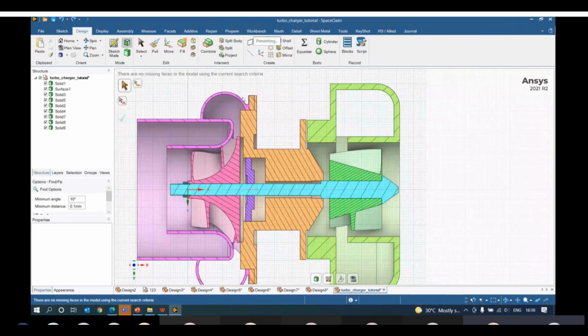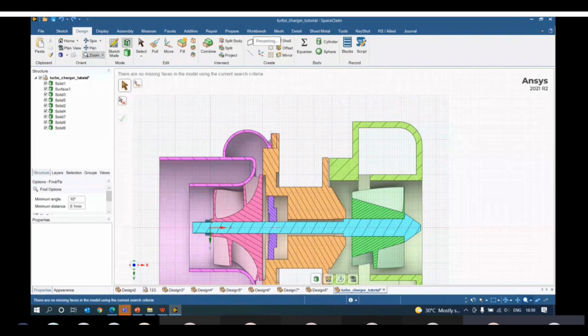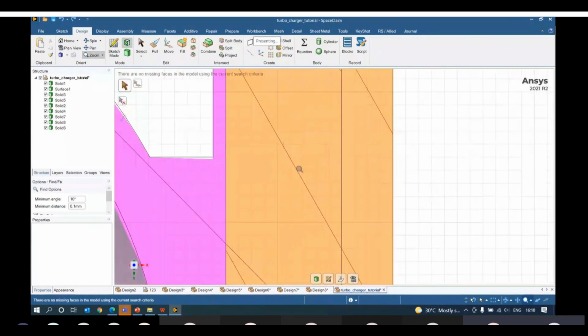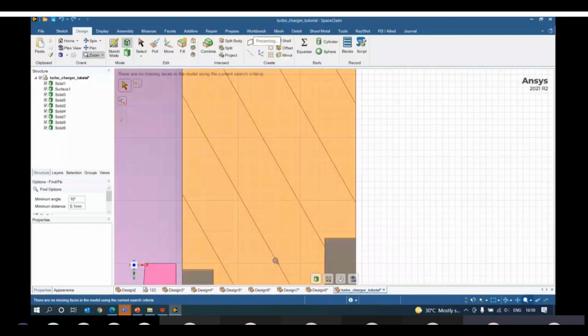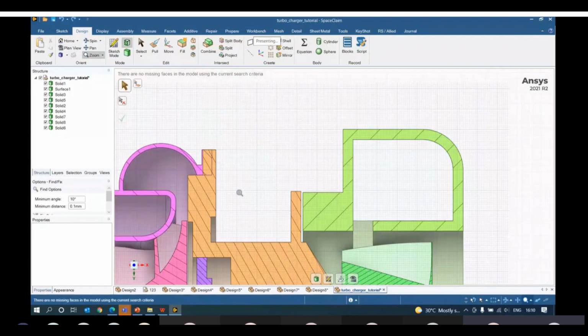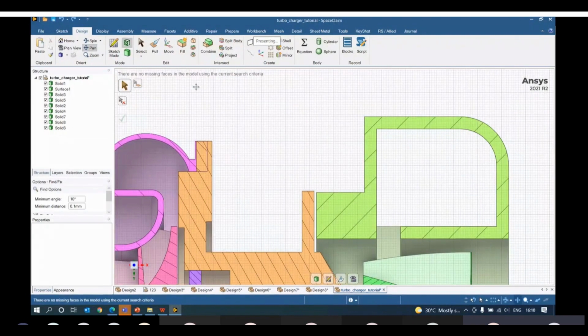And now here, if you look at it, you can see there is some disturbance in the flow of hatching, right? So here itself, you will understand, yes, there is a problem. But when you look at the other portions, it's clear, right? So even in this way, you can resolve the issue.